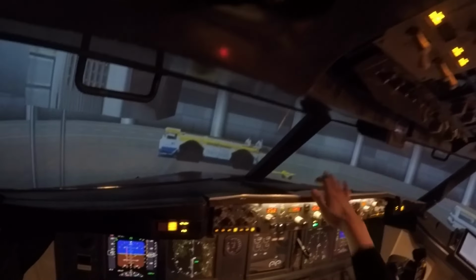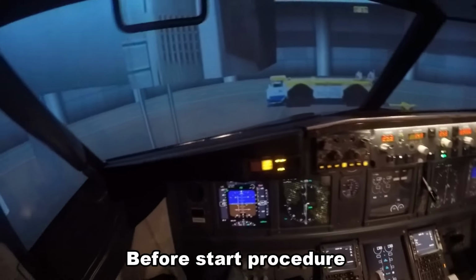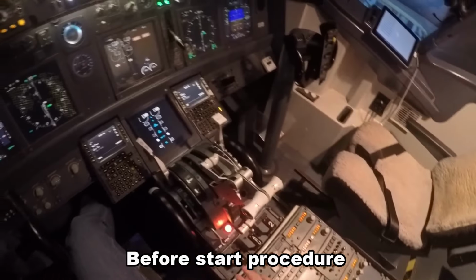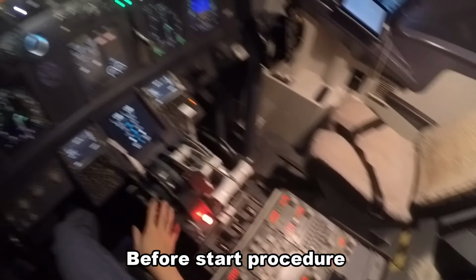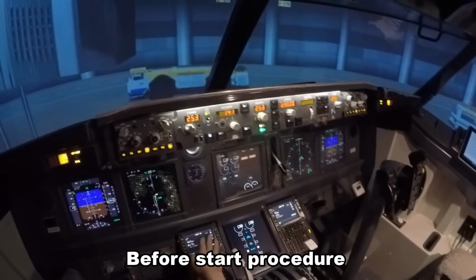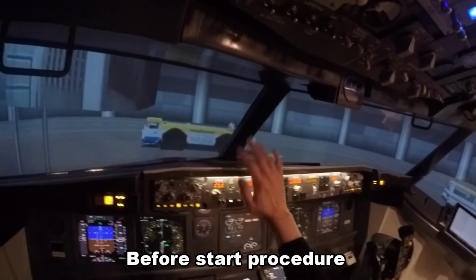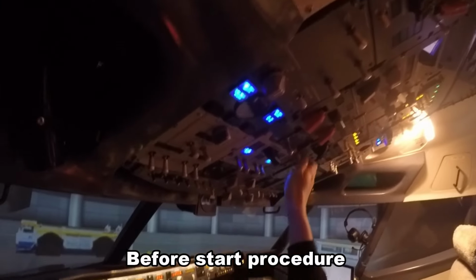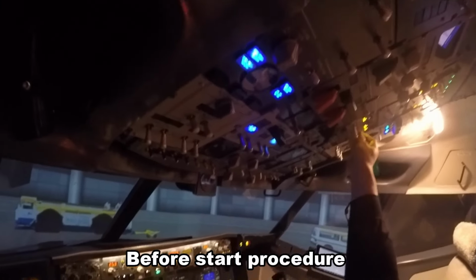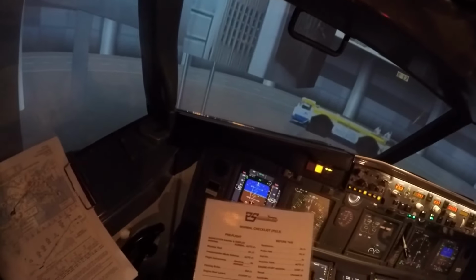Alright, so do before start procedures, flight deck doors closed and locked, rudder and aileron trim is set to 0 and 0. Our trim is 5.3, so that's set. CDU V speeds are all set. Our remote control panel is set. Windows are locked. Fuel pumps are going on. Passenger signs are on. Hydraulic panel is set. Anti-collision light is on. So we go through the before start checklist.